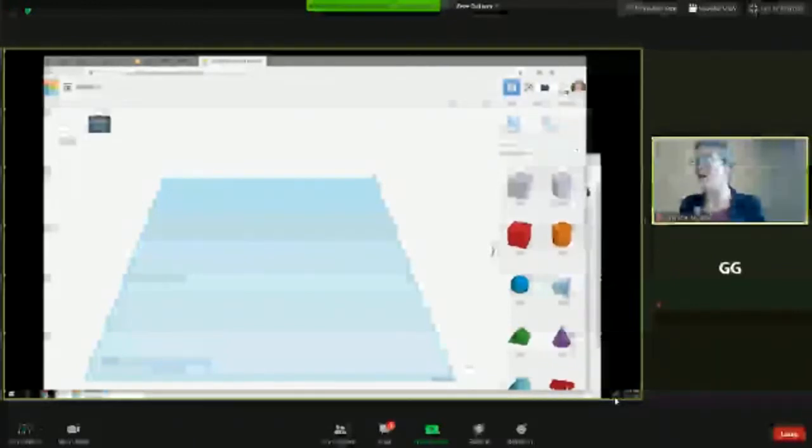If you want to select all or show all, you click this button here. If you want to group objects, once they're selected, you select that, and you can ungroup them. You can also align, and you can mirror. We'll also be able to export designs once they're done so they can be 3D printed as STL or OBJ files. This is the work plane that we see here. You can add more of those. You can add details to the rulers and also different shapes, as I mentioned, that you'll be bringing in and combining.